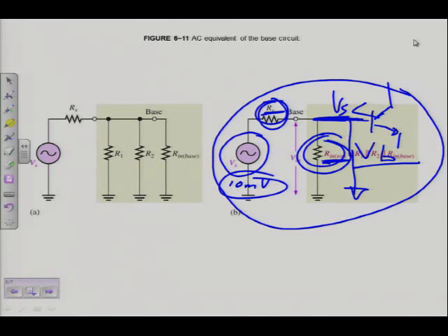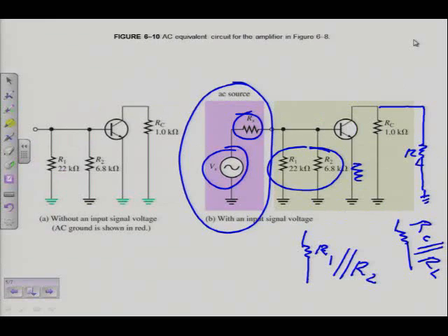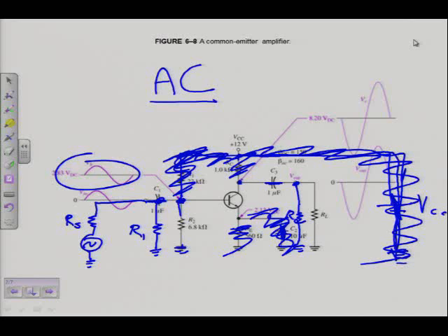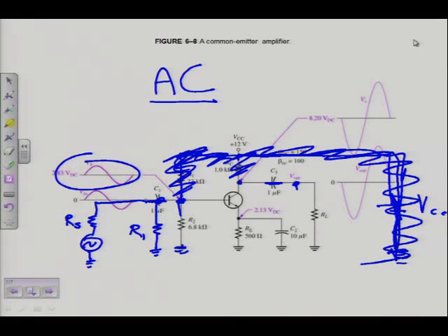Alright, the last thing for today: input resistance at the base. It's exactly what I told you earlier. If we can go back to our original circuit, you calculated in Electronics 1 R in at the base as beta times RE.